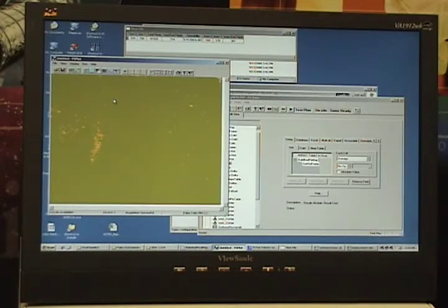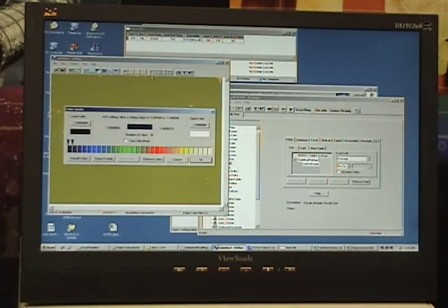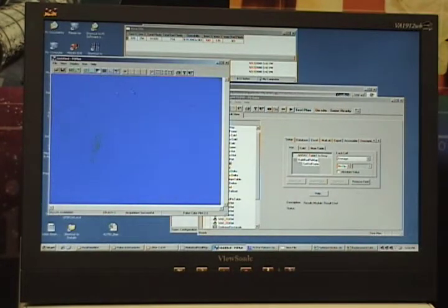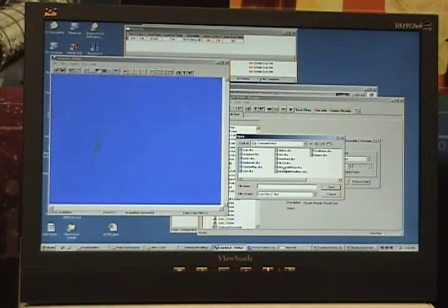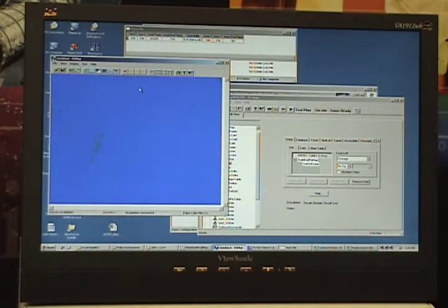We can view the bad pixel map and report in our PyPlot software. Good pixels have a value of 0, and bad pixels have a value of 1. The number of bad pixels is reported, as well as the operability of the device. We can also report the number of bad pixels in a key region of the device, such as the middle quarter.